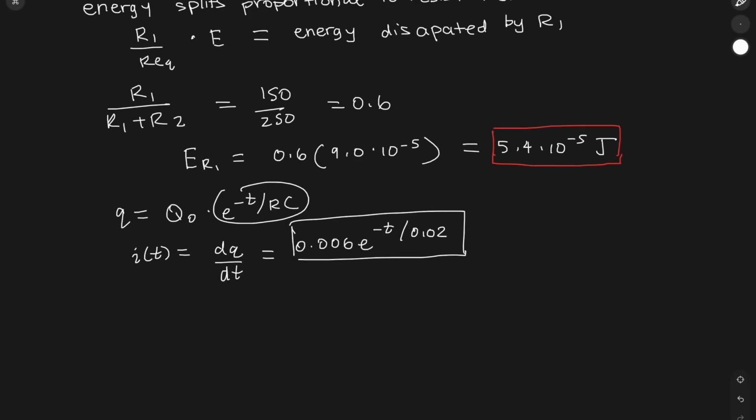The way to do that is calculating the derivative of power over a certain amount of time, which is, oh, sorry, not the derivative, the integral. It's been a long day. So it's the integral from 0 to infinity of I squared of t times R dt. Notice that R is a constant because R does not vary with time, because it's inherent to the resistors. Once we have this expression, we're just going to directly substitute the current expression here.